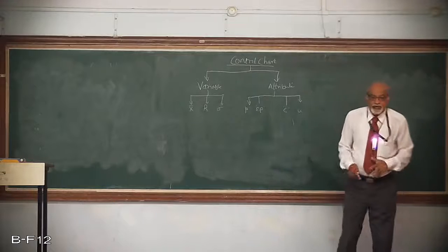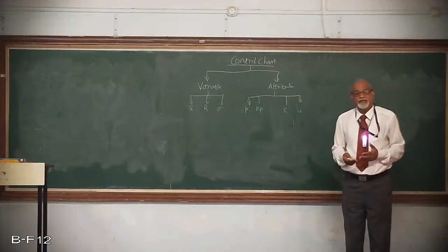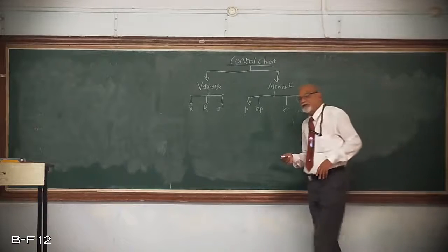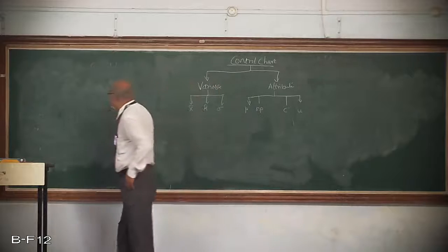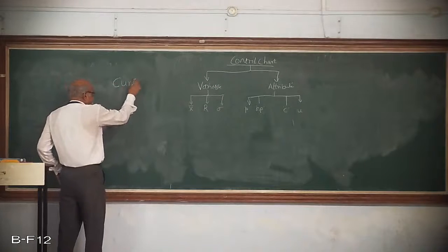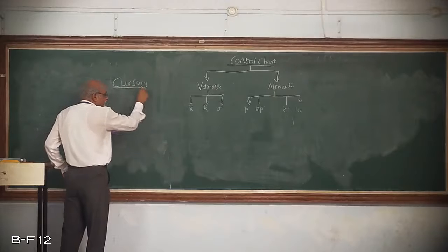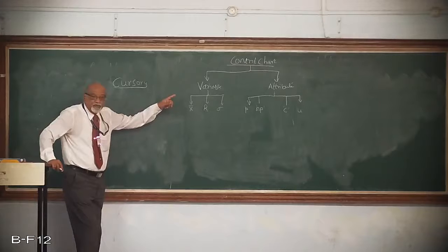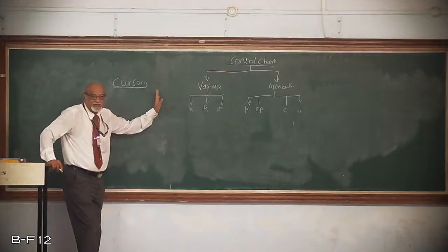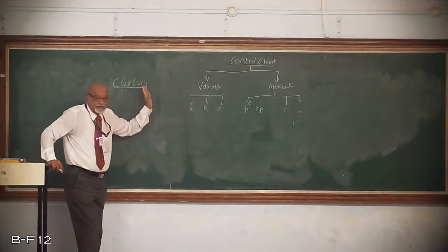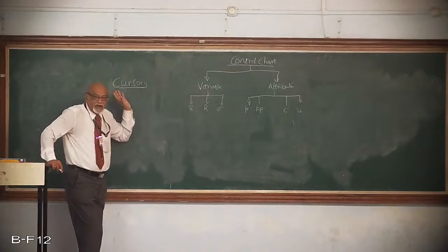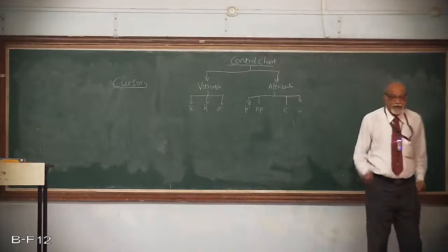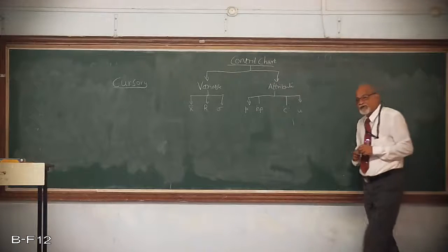It might be one or two measurable quality characteristics, and then it becomes more viable. Putting it another way, first we begin with control charts for attributes for cursory analysis, then we zero in on it, then we go for control charts for variables for detailed analysis. That is how we can control the quality effectively.